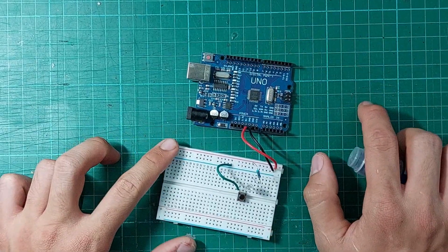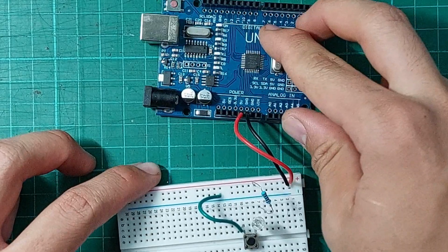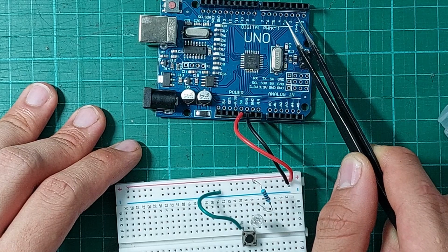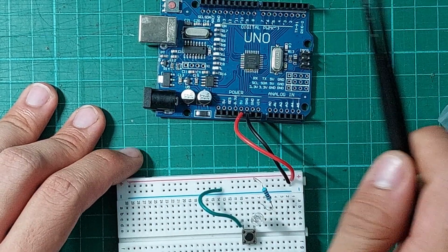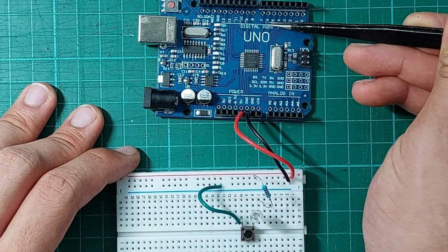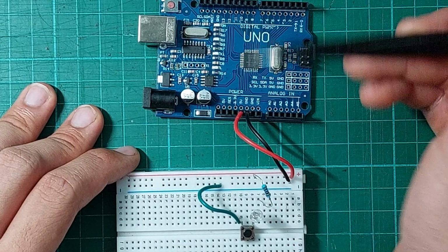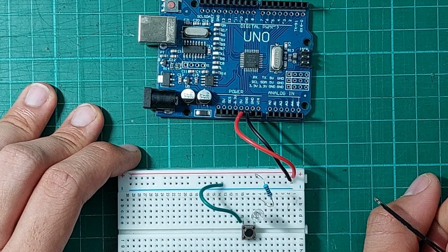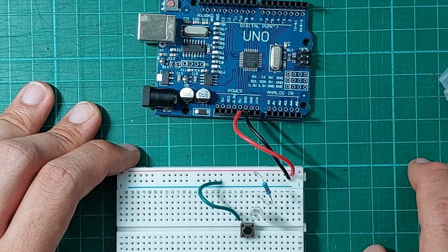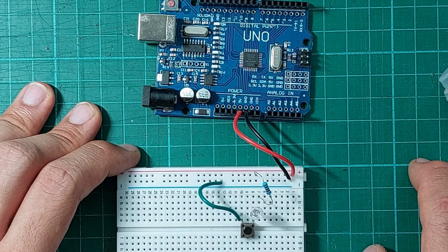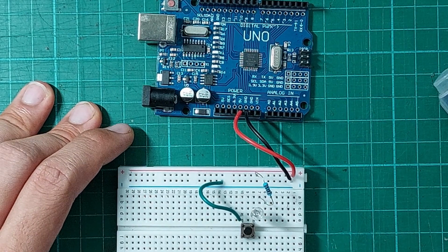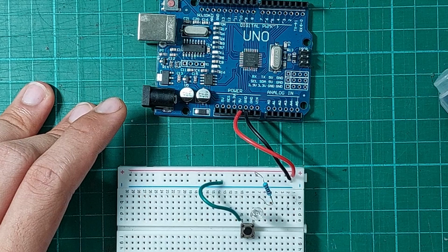Okay, so going back to our example over here, we see that we have a bunch of pins. Over here we have some digital pins, 0, 1, 2, 3, and then we notice this strange thing, this squiggly sign, this tilde sign over here. Pin 3 has this tilde sign, 5 has it, 6 has it, 9, 10, and 11 have it as well. What this tilde sign means, well, over here it does say what it means. It says PWM. So it means that these pins are capable of doing this on, off, on, off, and emulate this analog output by just turning the digital output on and off really quickly.